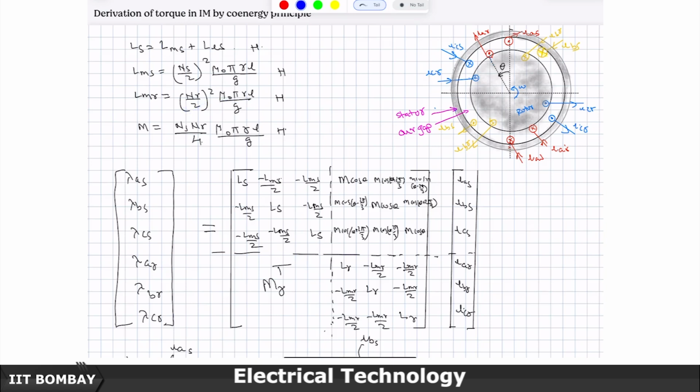recurs. Just look at this snapshot where we have drawn it: it is rotated by theta degrees in the positive anti-clockwise direction. So, the corresponding conductor is theta degrees later. If this is right now the axis of the A phase winding of the stator, then the axis of the A phase winding of the rotor is like this. Once you have marked this, diametrically opposite comes this term, then go 120 degrees on the rotor circumference further, you get the yellow colored windings, and then from here you go another 120 degrees and you get the B colored windings, or the ABC windings of the rotor.